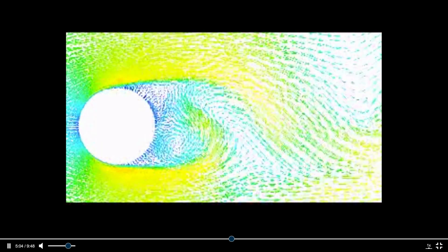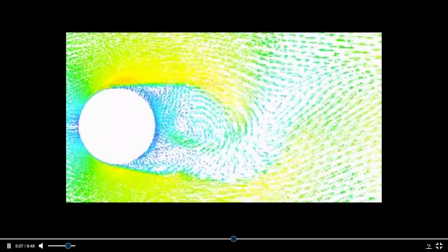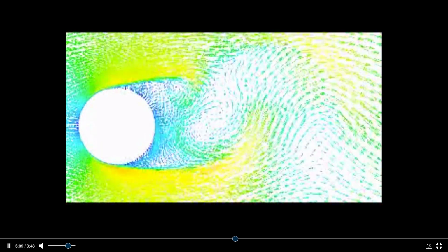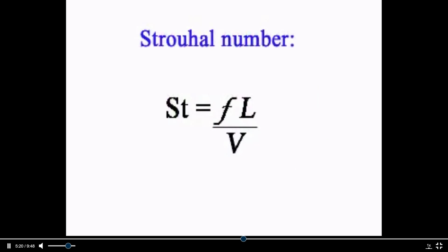This is named after another father of modern fluid mechanics, Theodor von Kármán. A CFD solution also shows Kármán vortex shedding in the same Reynolds number regime. Finally, when the Reynolds number reaches values above a few hundred, turbulence begins to dominate the flow pattern. Another dimensionless parameter, the Strouhal number, gives a non-dimensional frequency for such periodic flows.